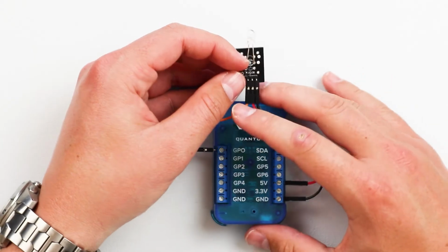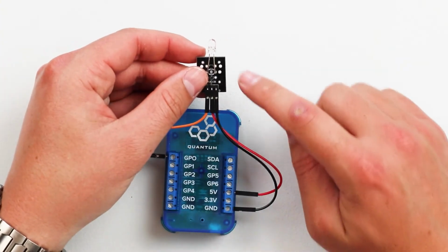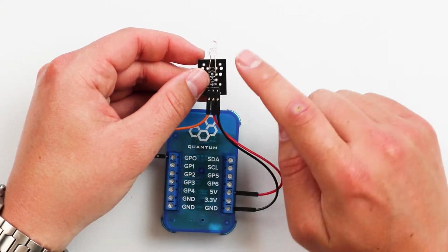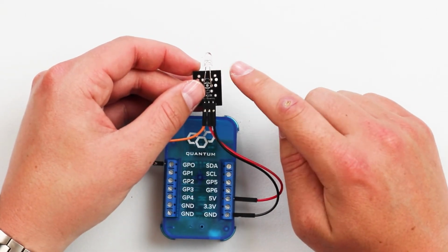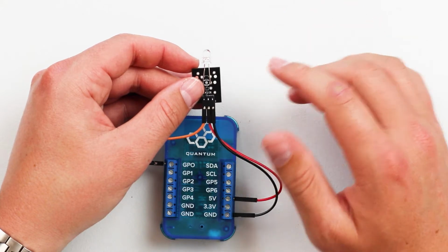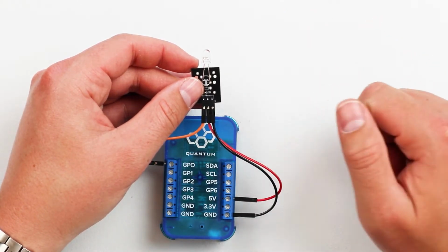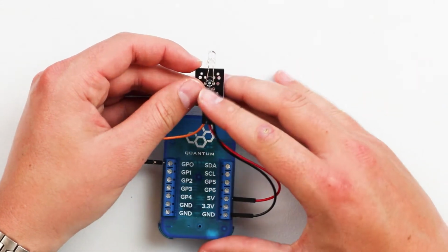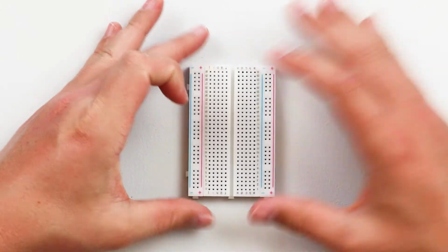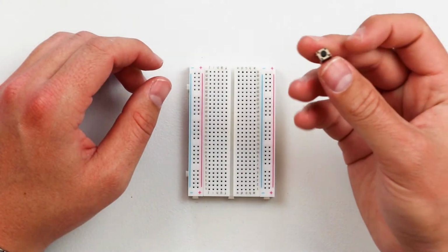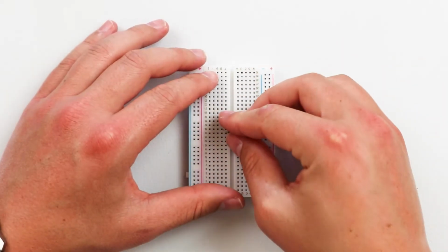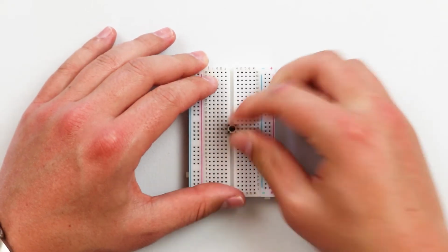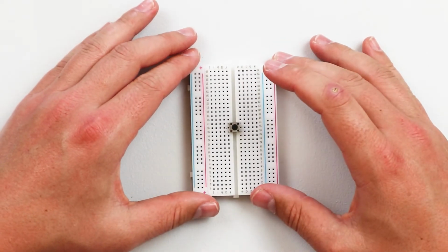Next, for this video, I'll be creating a simple push button that we'll be using to send the IR hex codes from our system out the IR emitter. That way we can control an IR device from a physical push button as well as an interface button on our computer or smart device. So I'll put this off to the side. I'll bring in a little breadboard here. I have a little push button right here, and then I'll connect that to the breadboard like this.